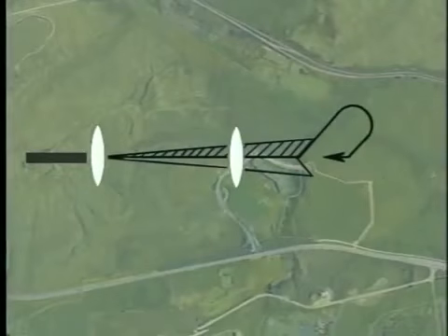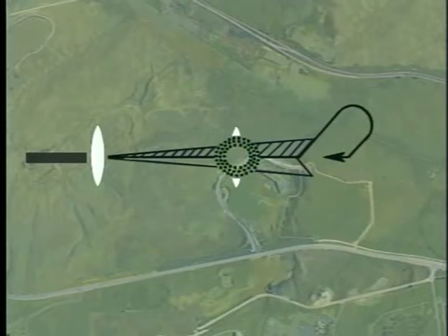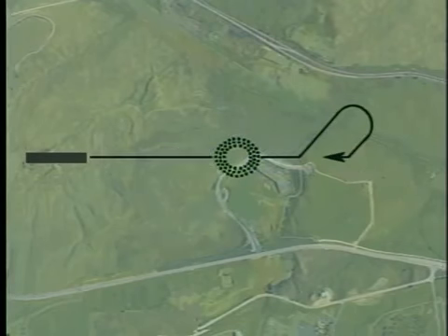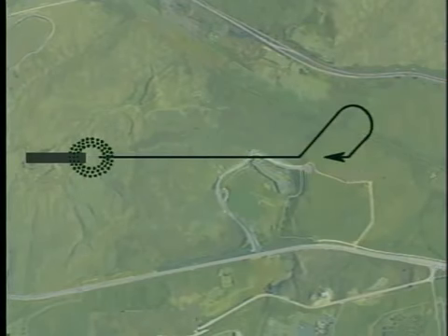An ILS approach procedure may incorporate a compass locator at the outer marker. At many airports, this same nav aid is used for the NDB approach. In this case, the station is located away from the airport, which requires a timed approach. At other locations, the NDB is positioned at the airport, where it normally becomes the missed approach point.